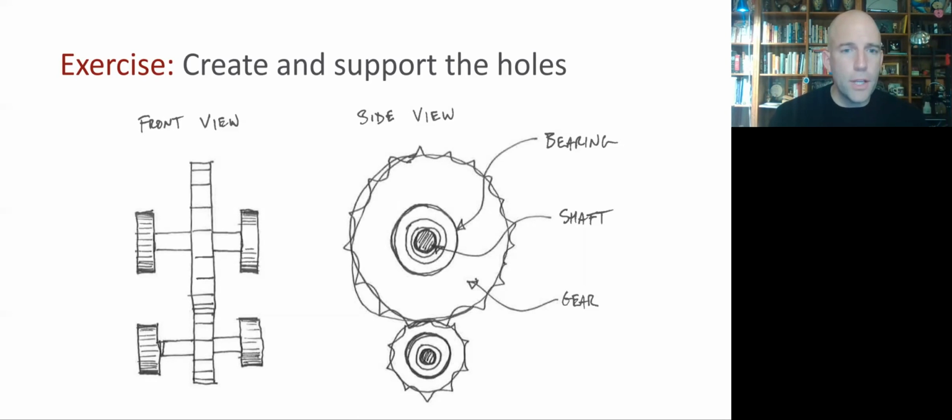And the other thing to think about is that these gears need to be located precisely with respect to each other. They need to be parallel, and these faces need to be coplanar, and the distance between the shafts needs to be as close to what we'd like it to be as possible.